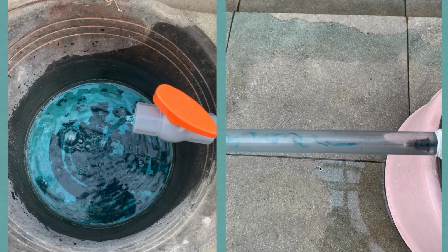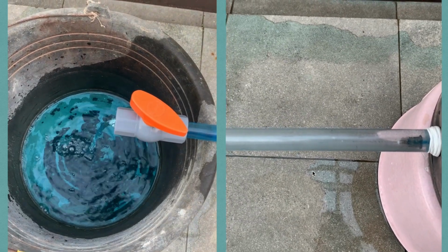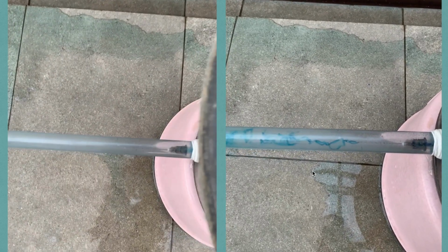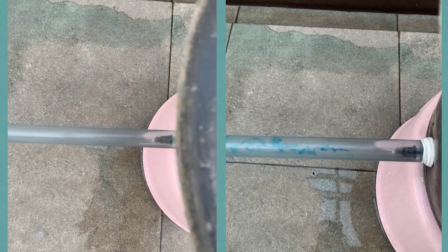Using the same procedures as the previous one, now we try to create a turbulent flow. After enough water is filled in the reservoir bucket, the valve is opened widely so that the flow rate is larger than the previous one. On the right, we can start to see the wavy and random paths of the dye streak. The dye streak is comparable to the previous one, the laminar flow. This flow is turbulent and chaotic, whereas the previous one is straight.